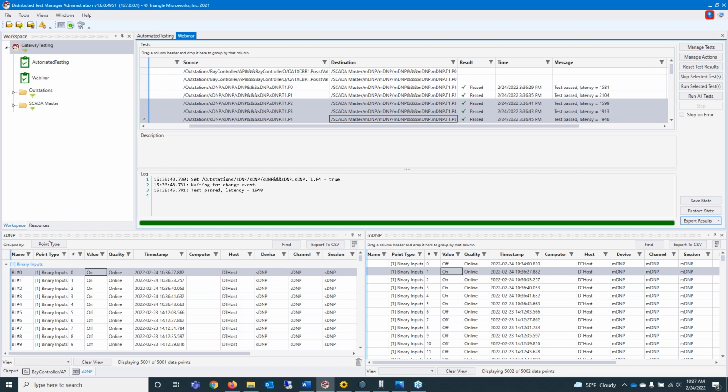Normally, do you have to test again in the field after installation of devices? Good practice says that you probably should test. You can obviously test in a testing environment when you're doing things like this with your gateway, and that'll make sure of a few things. If you're doing it in a simulated environment, number one, you can make sure that the device is able to do all the functionality that you need. So if you need specific class reads or specific timings, you can do all this in a simulated environment. Number two, you'd want to verify that the actual mapping has been done.